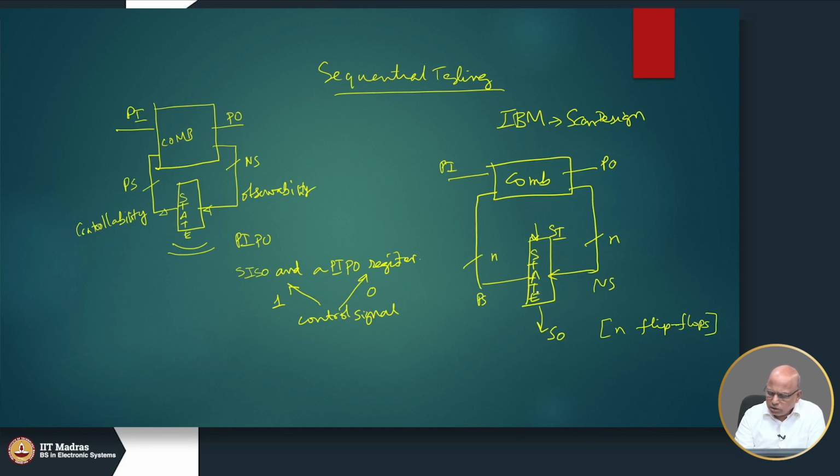When you want full controllability on the state register, that means you want to initialize the state register to some value, what we do is, remember I told you there is a control signal, we will call it scan enable.